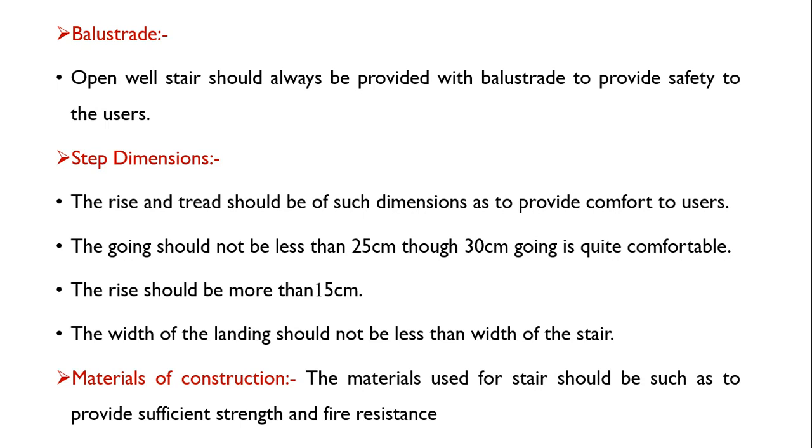Step dimension. What should be the step dimension as far as a good stair is concerned? The rise and tread should be of such a dimension as to provide comfort to the users. The going should not be less than 25 centimeter, though 30 centimeter going is quite comfortable. The rise should not be more than 15 centimeter. The width of the landing should not be less than the width of the stair or width of the flight. These are the requirements of a good stair.